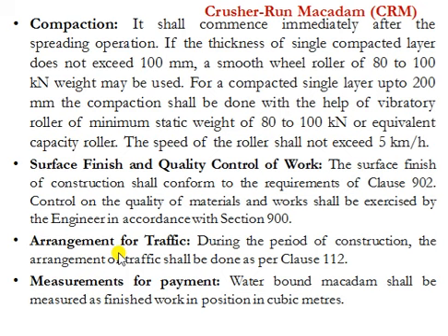And it should be noted that the speed of the roller should not exceed 5 km per hour. When the speed of the roller is maintained at 5 km per hour, all the surface of the pavement will get an even compaction.